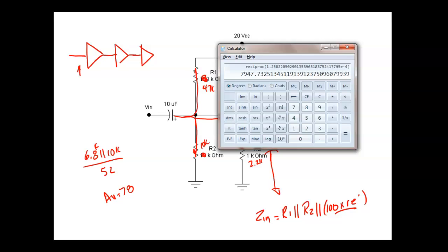Well, we get a real high gain, but we lower our input impedance, right? You understand? What do we get if we don't bypass it? Well, we lower our gain, but we get a higher input impedance. So that means if I've got a device that has a high output impedance, I would feed it into a what? I would feed it into an unbypassed one, so it doesn't have to supply as much current. And then the output of this one, I might feed it into a bypass, right? Does that make sense? So normally in stereos, we go through stages.